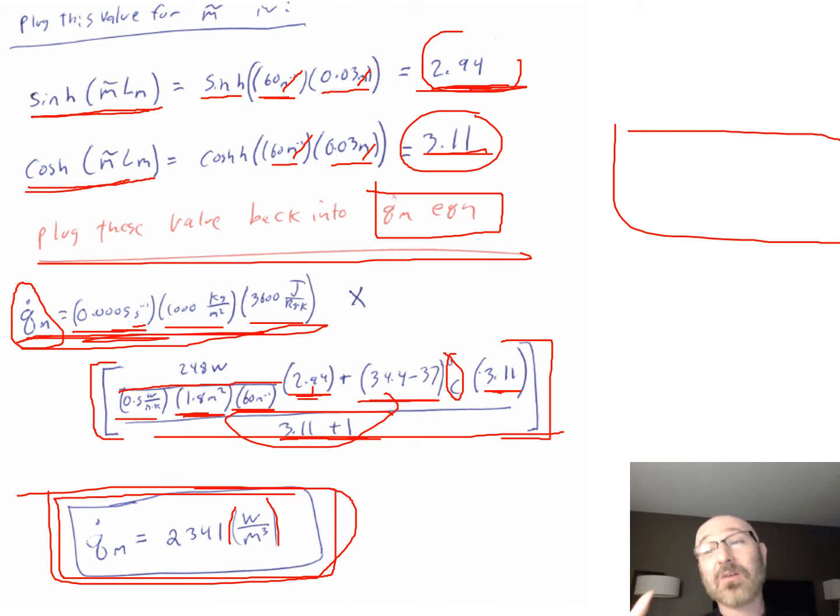So there's a lot going on right here. Make sure to break this down and solve each section individually, maybe even more broken down than what I've done here, in order to keep track of things. This is a good spot where you ask, do I switch over to a numeric solver or do I still attempt this by hand? You can still do it by hand, but I would almost suggest Excel would be a great spot. It might take a little more time setting it up, but once you have it set up, you are less apt to make errors in your hand calculations. You can solve for each term separately in different cells and plug them all into your one general equation at the end to get this value for your Q dot M.